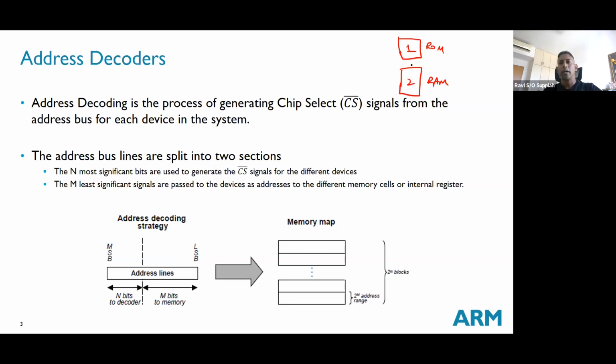From your hardware modules, you would know that for every chip, when I want to activate it, there's what we call a chip select line. There will be a chip select line that I need to activate if I want to talk to that particular component. In most cases, it is an active low chip select, so that's why you put the bar on top. When you put the bar on top, it indicates that it's active low, so you usually put a bubble there.